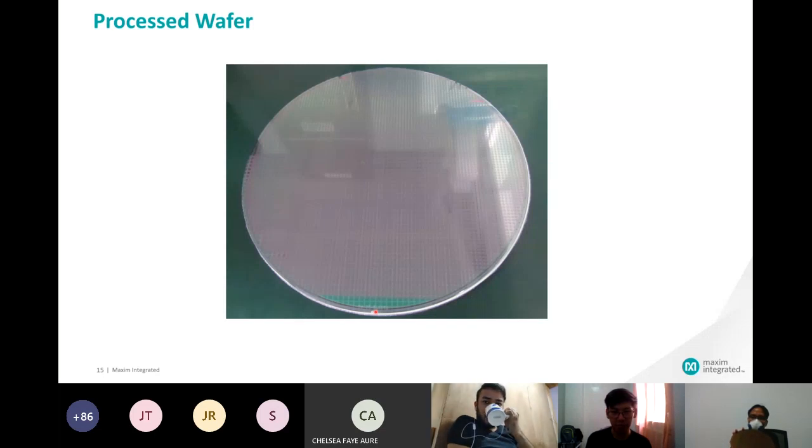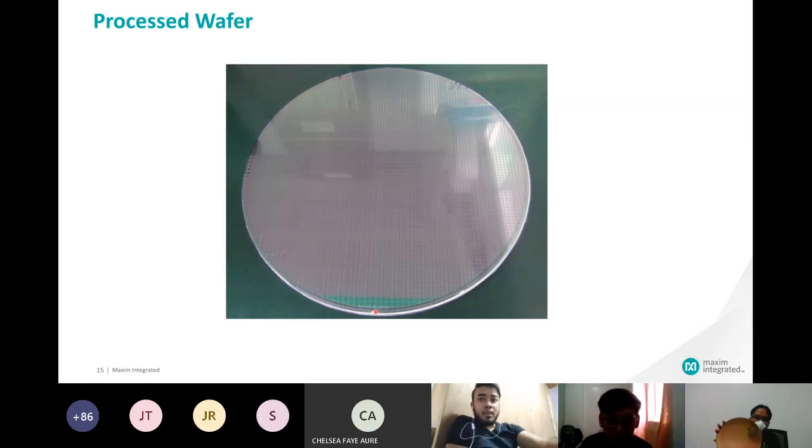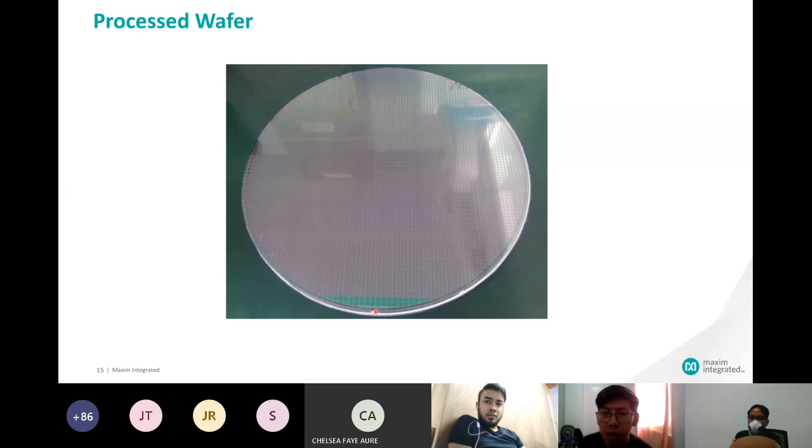Everything has to be aligned so that you can dope it, and you can covalent bond the silicon with the dopant, right? So that you can align and dope the silicon, you need to have a reference for the silicon lattice structure. That's why there's a notch in here. If you want to read more about it, it's also in chapter 1 of that book that I mentioned. There's a good discussion in there. So anyways, this is the wafer. It's an engineering wafer, so I can touch it with my bare hand. But in production, we're not allowed to.